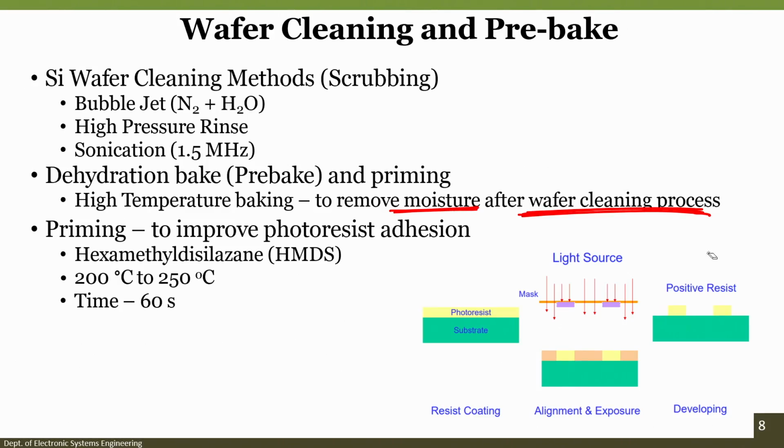In this case you can see here resist coating. So, this is the step: resist coating, soft bake, then expose. After expose you have developer. If it is a positive photoresist, you can see that the unexposed area got stronger and the exposed area got weaker when you develop the wafer.